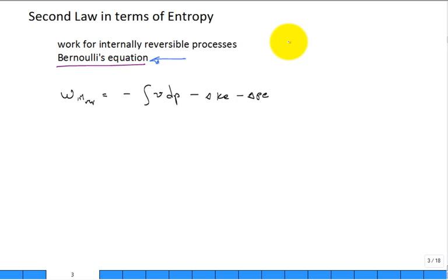What it said was, we have a little pack of fluid and it's flowing through the system. There's the little pack of fluid later. We're not going to do transient. This is steady state, so guess what? That path line is equal to a streamline of the fluid. So this is a streamline of the fluid. With simplifying assumptions, we'll say it's a frictionless fluid. In other words, inviscid, meaning no viscosity, negligible viscosity, fluid flow.